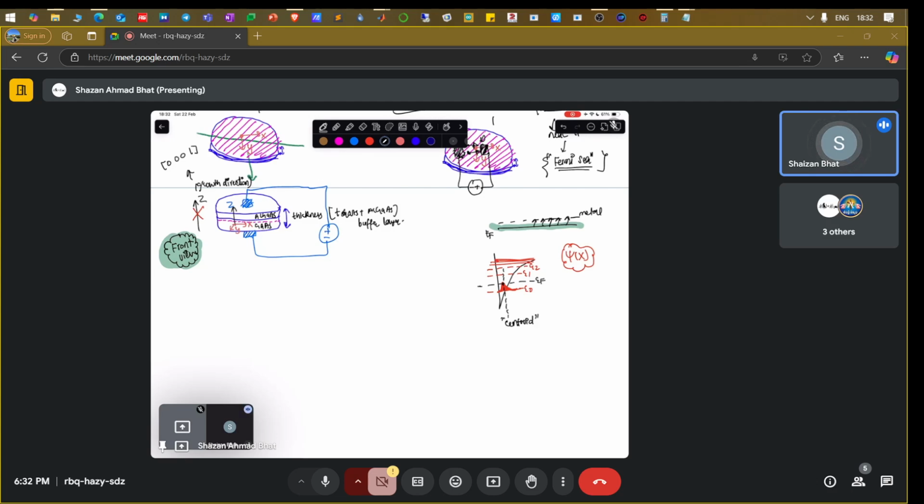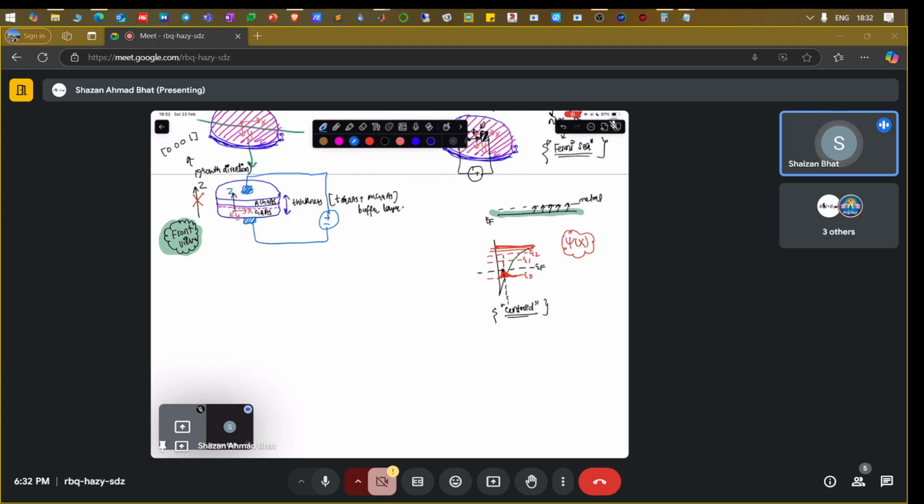And you can find the distance of the centroid. Mostly in the literature, you call this distance delta d, which is the distance of the centroid of the charge, where it peaks, from this particular surface, from the interface of aluminum gallium arsenide. Okay, so now this is for E0.